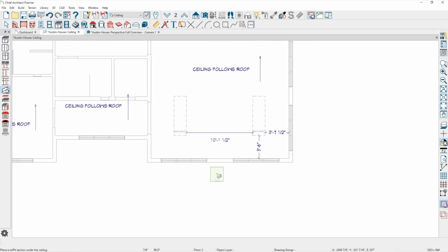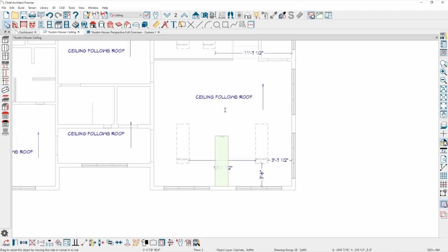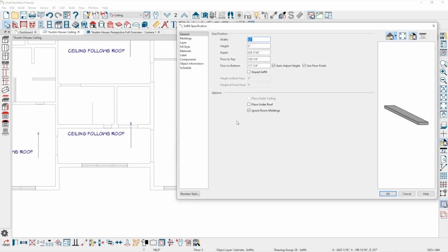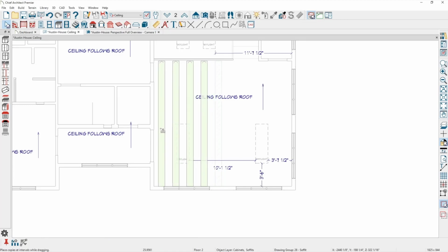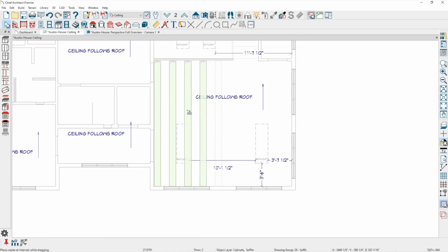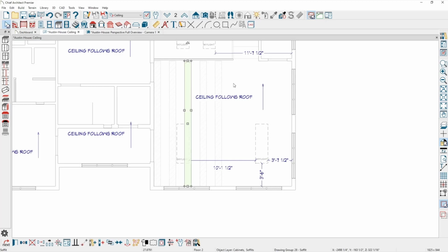And if I just put a soffit, let's see, right in here, and we just pull that back a little ways. One of the options when you have a soffit is there's an option to say that it's a sloped soffit, and you can place it underneath the roof, right? Oh, okay. And then maybe I'll make a couple copies of this. Fine. I'll just delete one of them over here, just so we can peek at it.